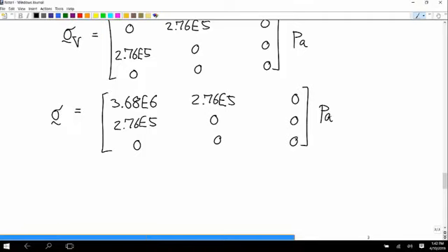And if this beam was made out of a fairly brittle material, and you knew that because it's brittle, it's most likely going to fail in shear stress, you would want to calculate the maximum shear stress produced by this loading at whatever point you're interested in. So how would you calculate that? Yep.